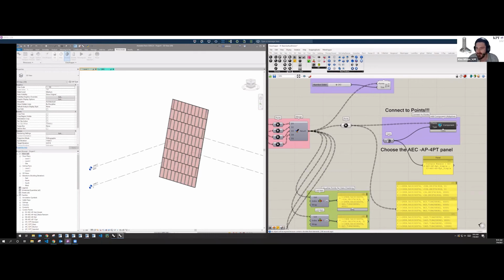Question about creating the profile in Grasshopper. You can't create parametric geometry inside the adaptive environment within Rhino.Inside yet. Creating those relationships between the points hasn't been added. So you could use Beam or something like that to create the geometry and then just bring it in. But if you are looking to create a fully adaptive system within Revit itself, you can't do that using Rhino.Inside yet.